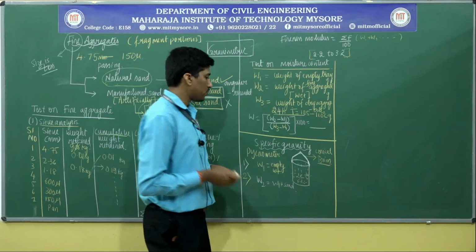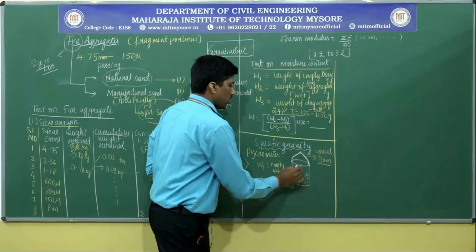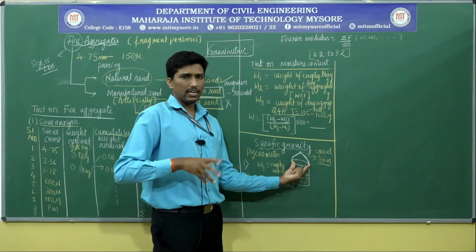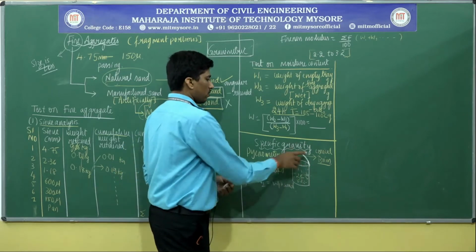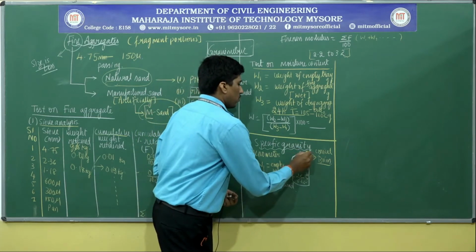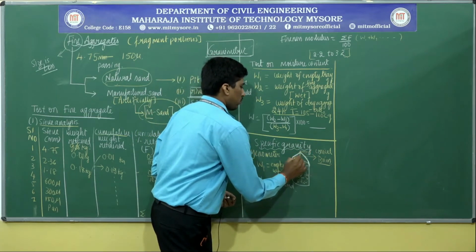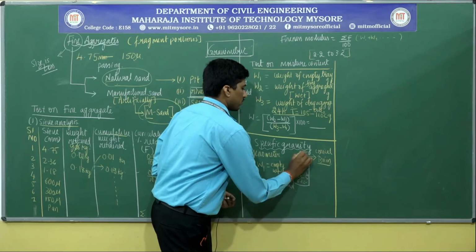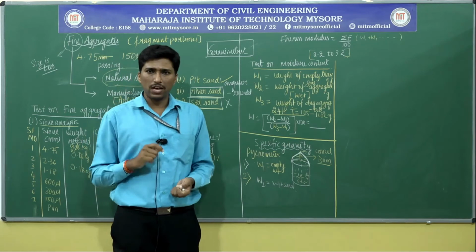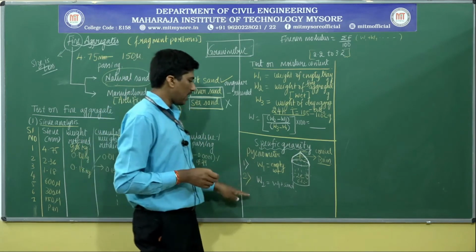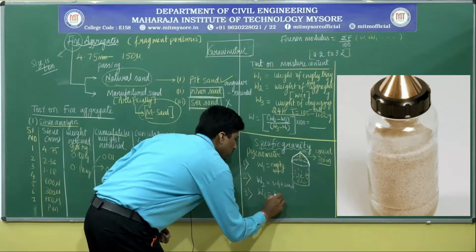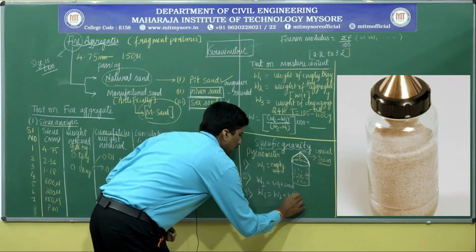For that purpose, the lid is closed once it is filled to the marked level, and on the top, where the brim is present, water is passed in to fill the remaining portion. You can also use a safety pin to expel some of the air bubbles, and fill it up completely. Finally, find the total weight. We call it W3, which is W2 plus water completely.